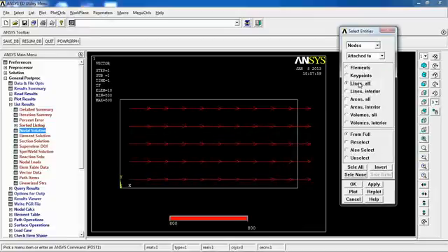So the basic idea is, now that I have selected one line, ANSYS knows only one line out of this whole model, and that is the line that I selected in the previous step. Now if I select nodes attached to lines, all, this means select all the nodes attached to the line that is known by ANSYS. The difference between this option and this option is, if I pick lines interior, the nodes at the beginning and end of this line are not going to be selected; only the nodes inside the line are going to be selected.